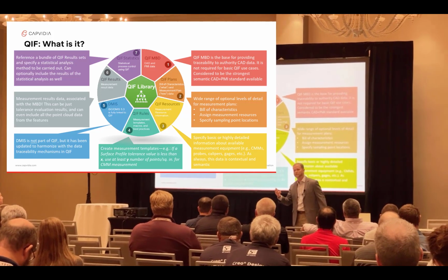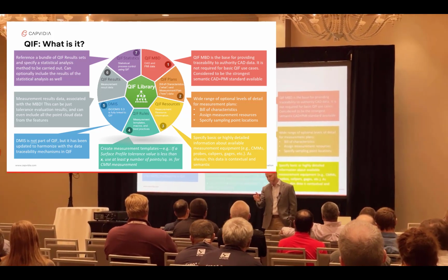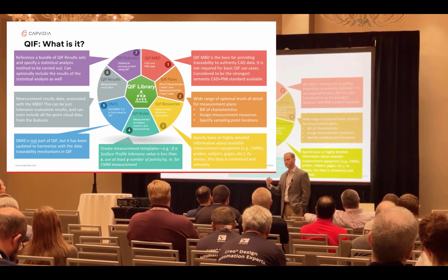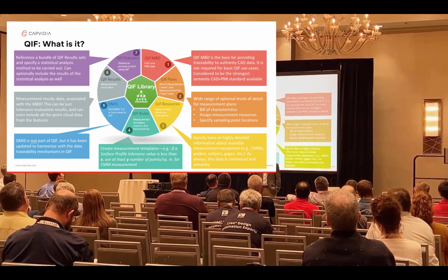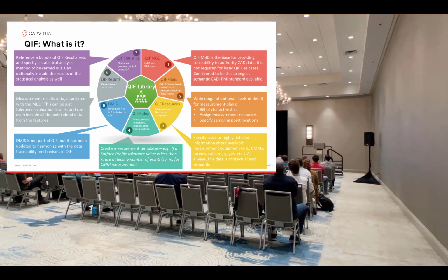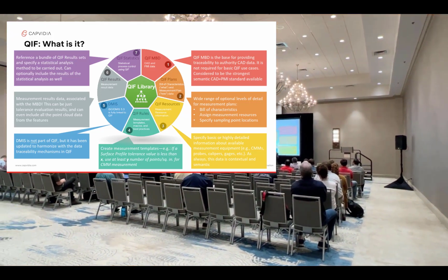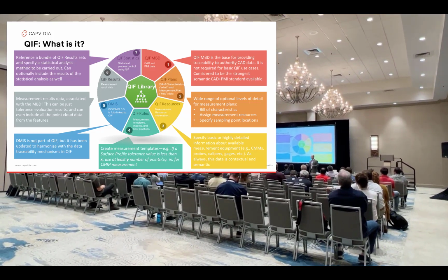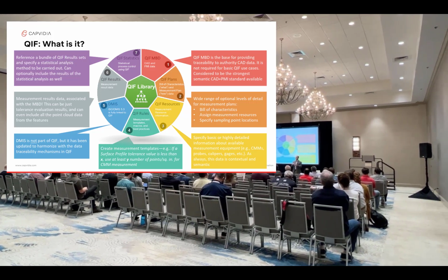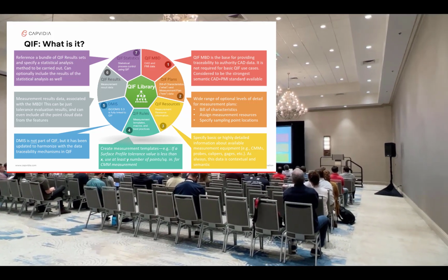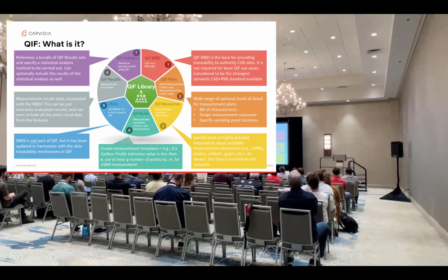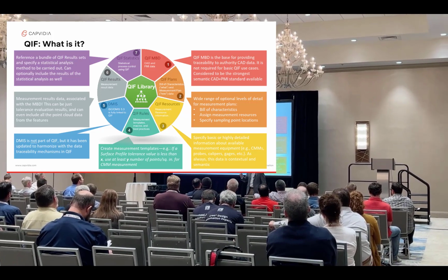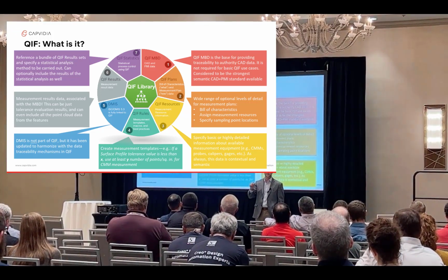The next thing is you want to gather some information about particular instances of your product and gather real-world information about that. And in terms of this digital twin context, often you think about a fully completed, maybe a jet engine, capturing vibration or heat coming from a jet engine or something like that. But at the manufacturing level, the same concept exists at the component level. And what we're talking about in terms of the actual data at that stage would be your measurement data, the data that you've gathered. And so that would be the second component necessary for this digital twin concept.